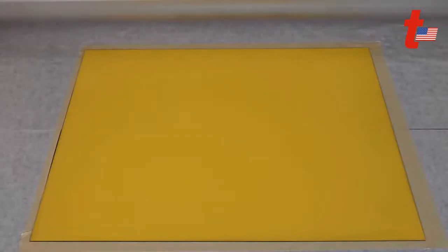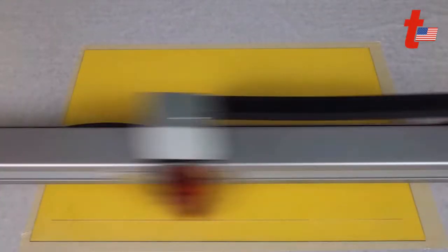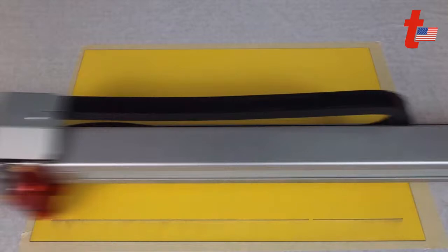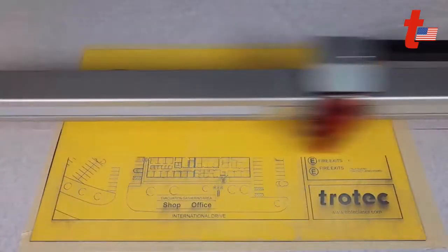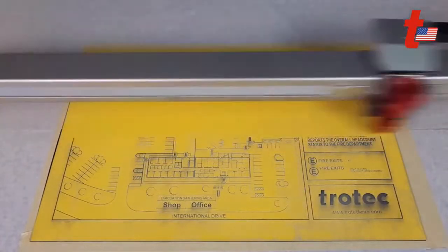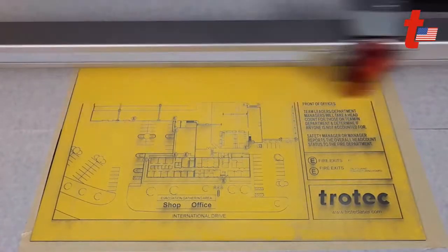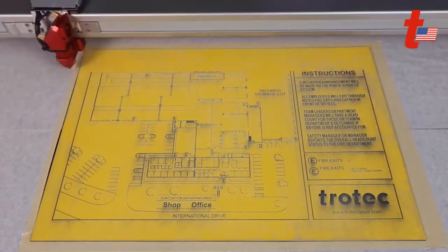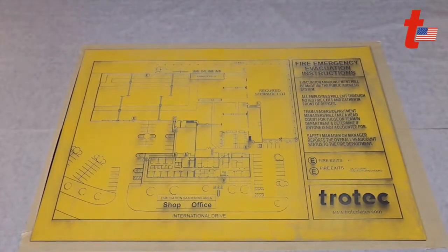And here's the actual process of an engraving. So this is a black core with a yellow surface. My video will run here. There we go. So what this does is it works just like any engraver's plastic. You will see a little bit more staining because the cap layer or the top layer of this material is much thicker. And so it does require a lot more laser power to punch through. Sometimes it is maybe easier to run multiple laser passes because this way you don't remove as much residue in between. It can give you a little bit cleaner response so you don't have that residue you see here.